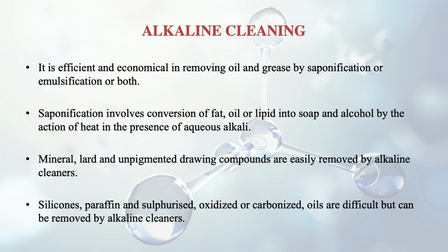Silicones, paraffin and sulfurized, oxidized or carbonized oils actually are difficult to be removed by this type of process. So these are the limitations of this alkaline type of cleaning. Further we move on to the acid, the second subdivision of the chemical type of cleaning, acid pickling.